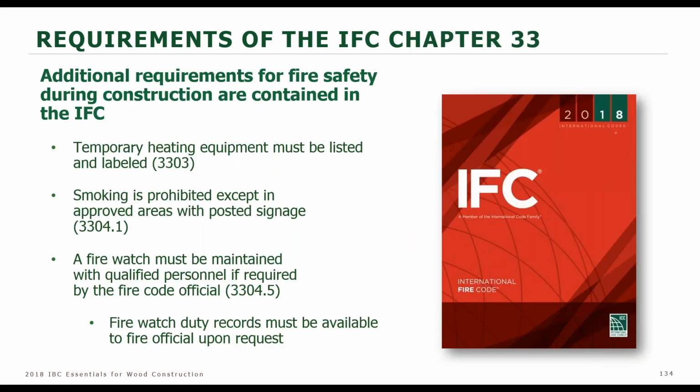I mentioned the fire code, temporary heating equipment, chapter 33, provisions for those, smoking, no smoking. Fire watch, 3304.5. And these were greatly strengthened, by the way, in the upcoming 2021 code, where the contractor will be held responsible for keeping records of inspections by their fire watch personnel that could be looked at by the fire official when he or she does their inspection.